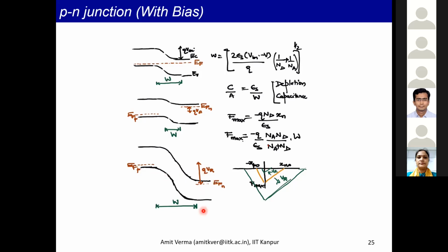Sir, I have a question. What is the effect of the polycrystalline nature of the material on these band diagrams? That's a very good question. I'll deal with it in transport, actually, it's more complicated. Most of the time when we do TCAD simulations or try to model the devices, we don't consider the polycrystalline nature in the band diagrams.